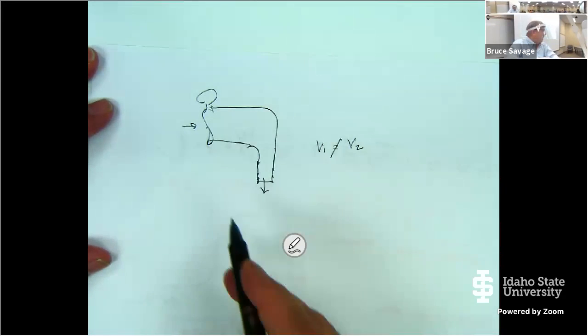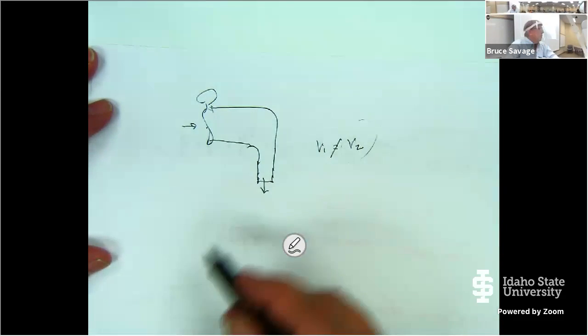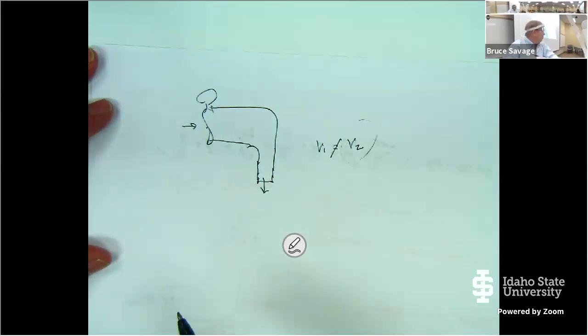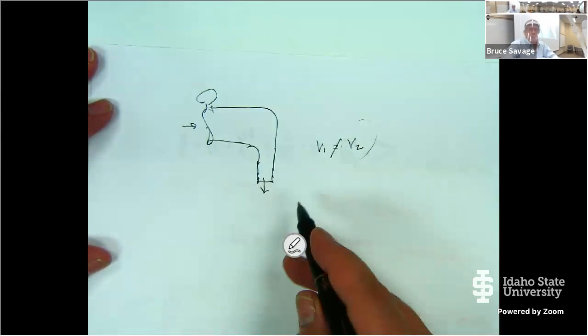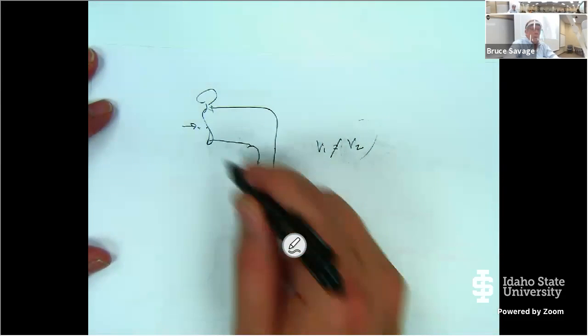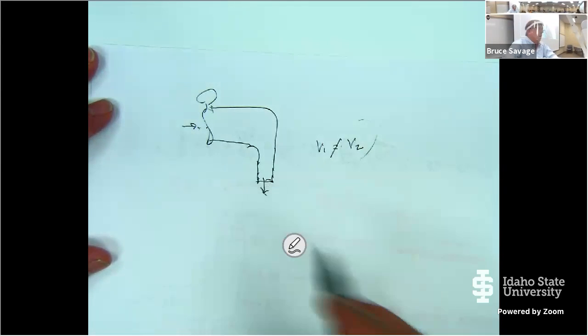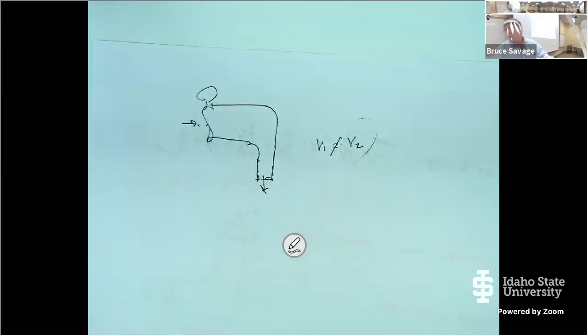So without any kind of head loss, I can make the assumption that there is no head loss and still solve for the different velocities. Or I can solve for a flow rate, actually. It's easier to solve for the flow rate, and then based on the area of this, solve for the velocity in each one of those. Are we comfortable with that? Not? Raise your hand. This is the time to. Okay, seems like everyone's comfortable.